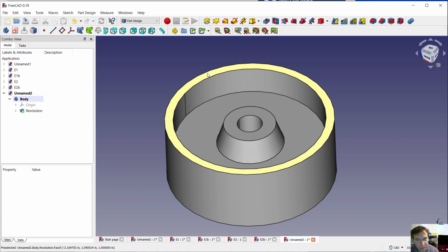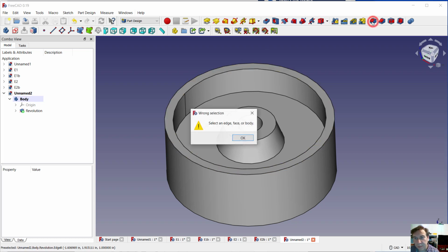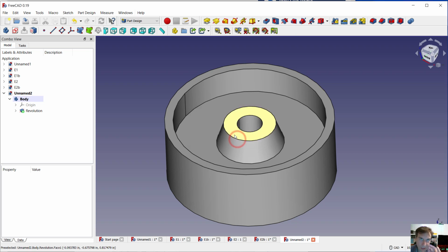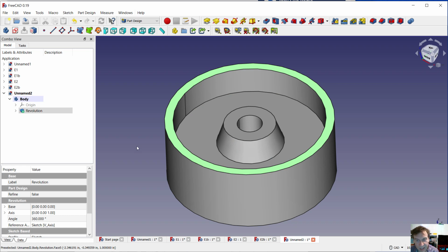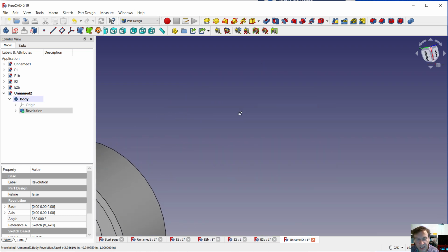Anyhow, only two other CAD systems could do what this can do. You could actually add fillets on an entire face, which is really a time saver. So go over here to the fillet tool. Oh, you have to pre-select in this. Select this face and shift and roll to the other side.